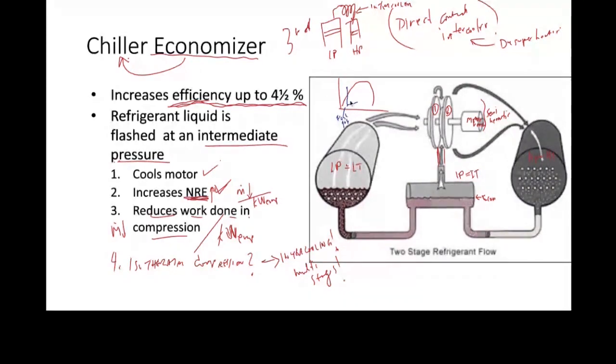And then the liquid is going to absorb heat as it boils, and then it's going to get superheated, and then what I can do is compress it adiabatically to some high pressure and high temperature, and I have lousy volumetric efficiency and all that kind of good stuff. And we've got this type of situation going on here.